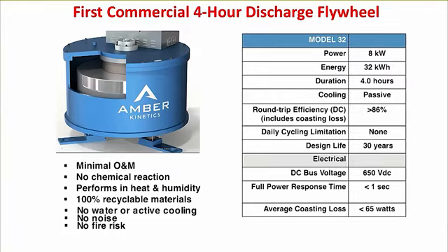Okay, in terms of efficiency, it turns out efficiency is quite good, greater than 86% round trip for this thing. There's no limitation on cycling. Of course, it takes 4 hours to discharge fully, if that's the objective, and 4 hours and some change to charge, because one has to put back the losses. And then other regular details, it's pretty fast in terms of response, on a 1 second time scale.